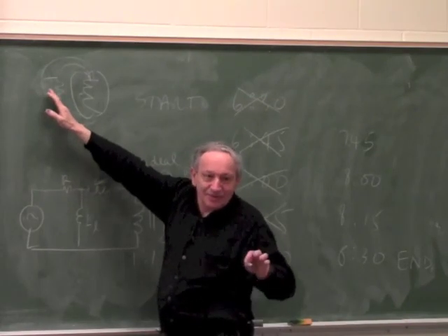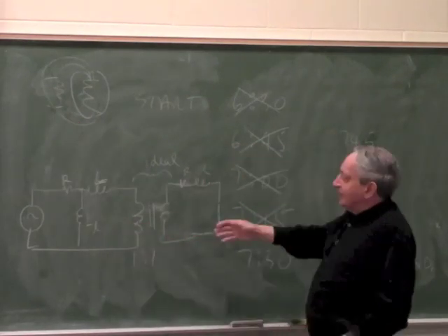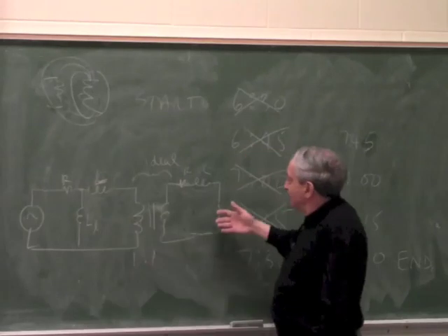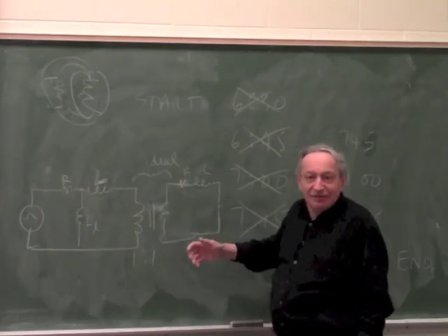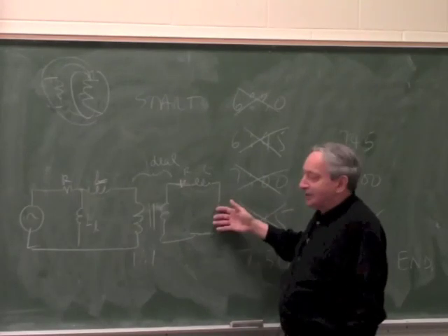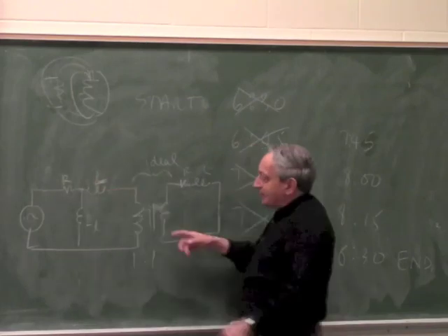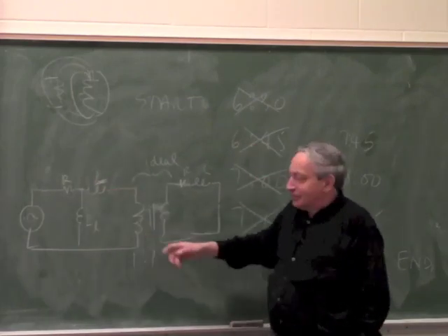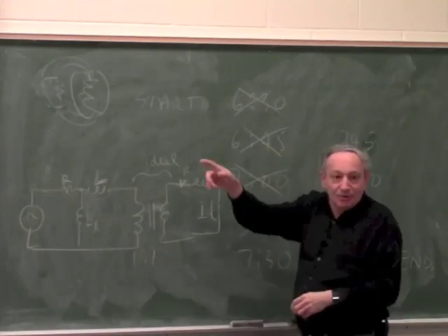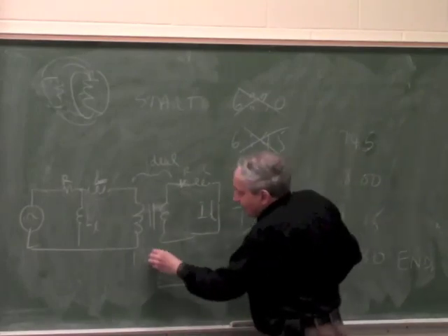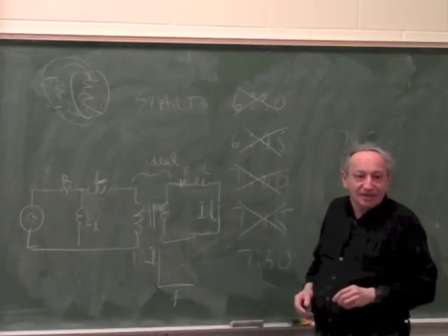I know I'm going very fast through it, but when you take a transformer like this, at zero frequency, there is zero current here, because there is no change of flux. But at a very high frequency, there is also zero current here, because at very high frequency, this inductor will limit the current. So if you draw I, which is the same as torque in a motor, versus frequency, it doesn't look like this, like it would look in an ideal transformer.